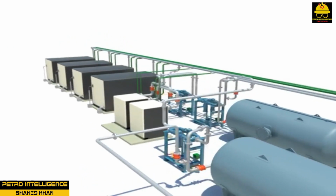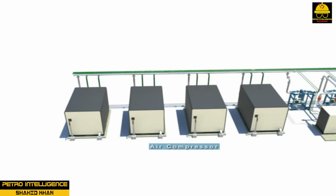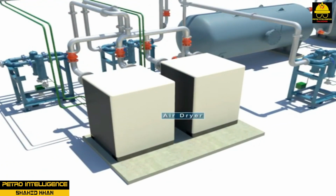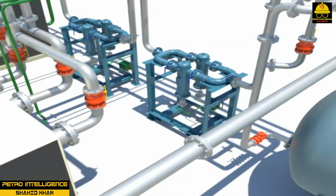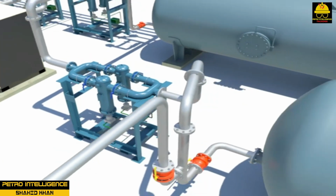Instrument air system pressure is protected against low pressure as a result of excessive utility air usage by an upstream pressure controller in the utility air system. This control valve will close off if the instrument air header pressure falls below 95 psi. It is important to maintain the instrument air system pressure at its normal controlled pressure of 105 psi because some control valve actuators begin to malfunction when the pressure drops below 60 psi.